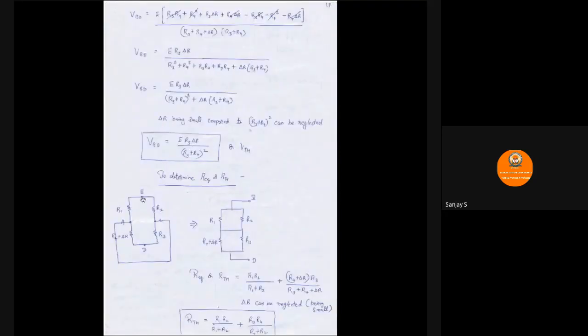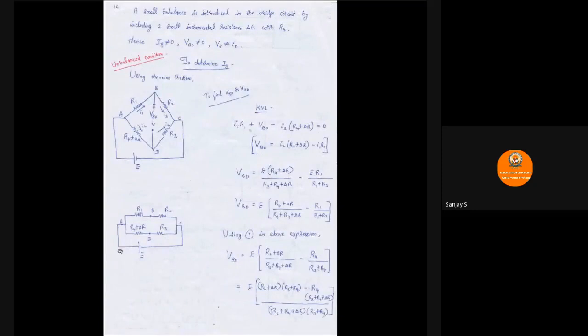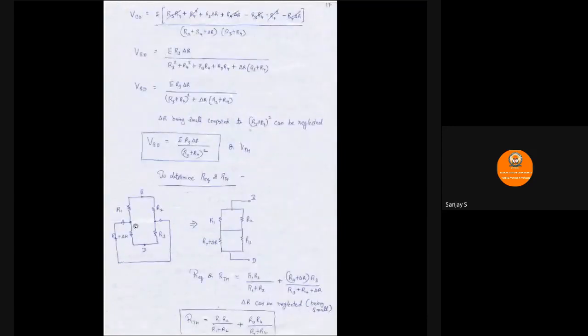So I have just redrawn the circuit in the other fashion to show you this. You can see the location of the respective resistances are between the same terminals. I've just reversed it, I have drawn it vertically. So the voltage source E, I have short circuited over here. No current source is there here. And then A and C has been shown here. Between A and C, I had a source which I have replaced by a short circuit or a line. So AC, I have shown it outside here. A and C is the same whether you connect it from outside or from inside. So in the next diagram, you can see I have connected from inside.